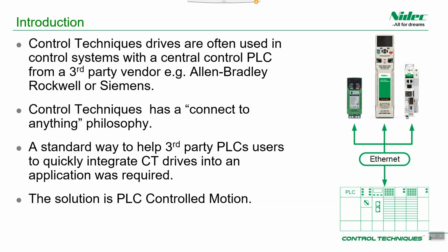Control Techniques drives are often used in control systems with a central control PLC from a third-party vendor, something like an Allen Bradley Rockwell or a Siemens PLC. Control Techniques has classically had a connect to anything philosophy, so we've supported lots of third-party vendors' communications protocols, things like Profinet, Profibus, DeviceNet, Ethernet IP.